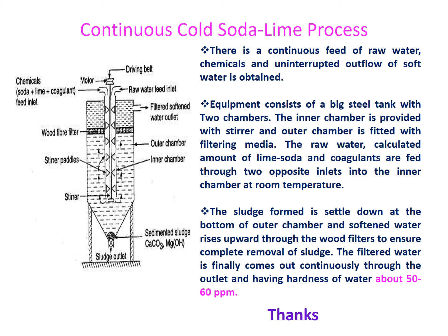Now another method, the continuous cold soda lime process. As its name indicates, in this method we are doing two things simultaneously. One is we are feeding raw water from this inlet, and chemicals like soda and lime and coagulants we are introducing in this chamber from this inlet, and a mechanical stirrer is also equipped here.